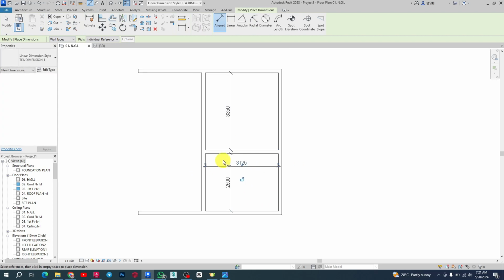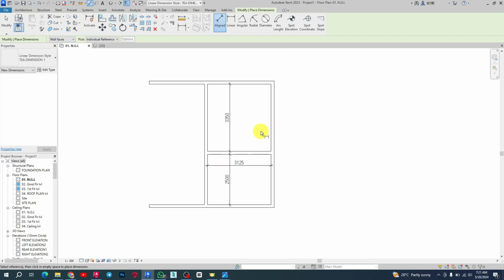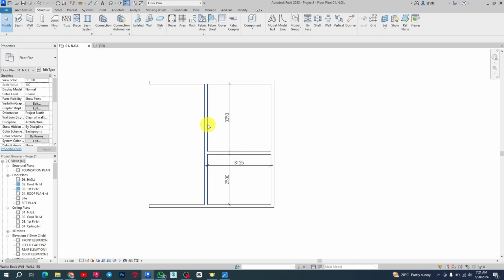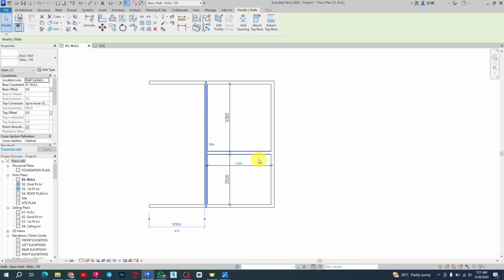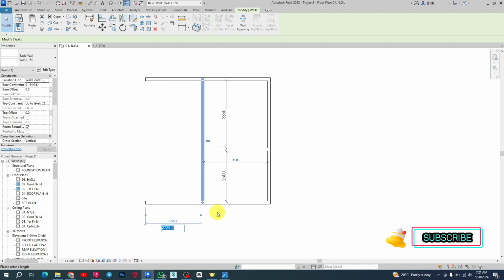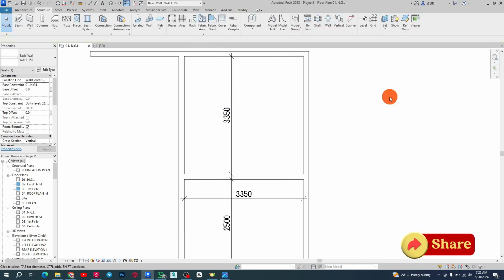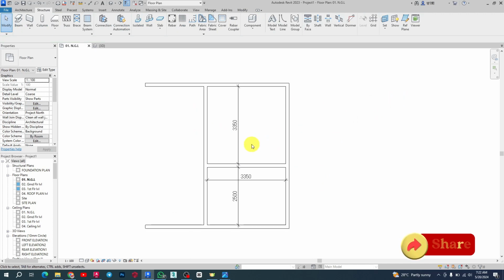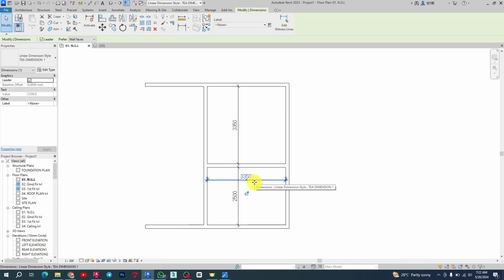Say probably you want to work on this drawing, let's have it from there. Let's just have it working. And Revit is automatically updating, right? If I just click on this one and change this dimension, probably I want this to be 2500, you see these other dimensions will update automatically to follow that dimension, without you going back like in AutoCAD to select again and place your dimension.